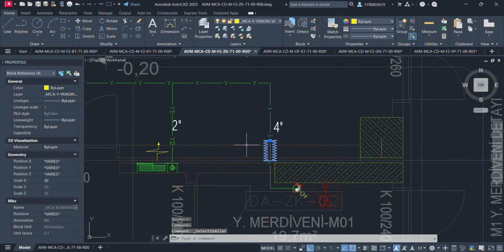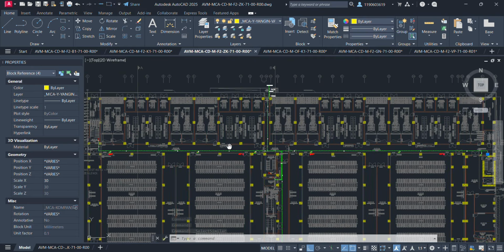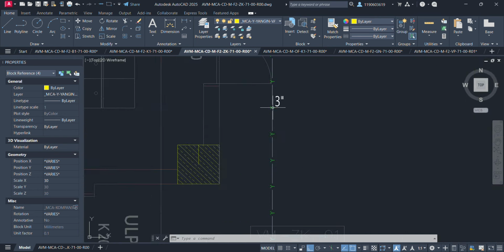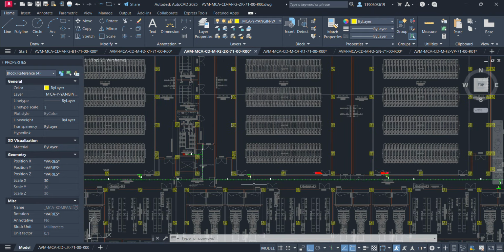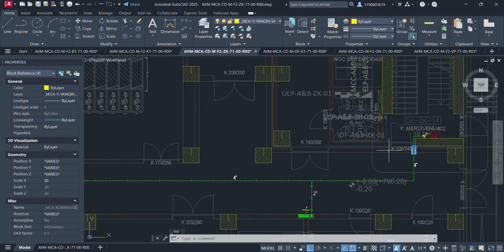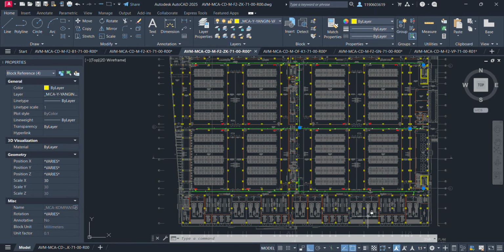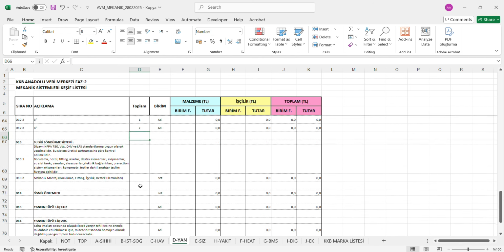Flow control. The collector also helps in controlling the flow of fluids by regulating pressure and the amount distributed through the different pipes. This helps prevent overpressure or leaks that could arise due to imbalance in flow. Space and efficiency. Collectors can reduce the need for multiple connecting pipes, as they allow several lines to be connected at a single point, thus saving space and reducing complexity in systems.